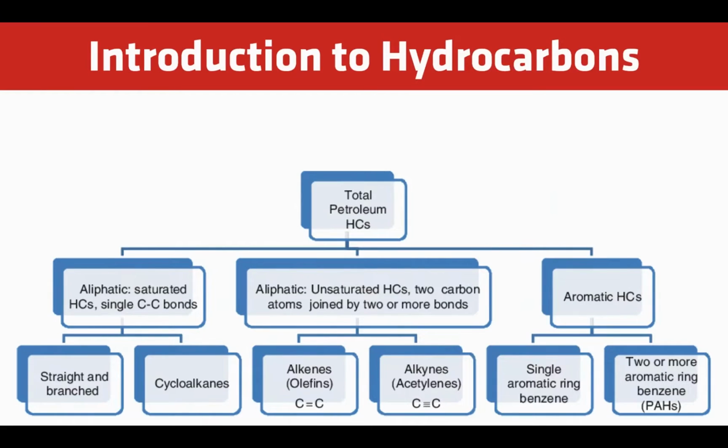There are three main categories of hydrocarbons, characterized as total petroleum hydrocarbons or total oil and grease. Saturated hydrocarbons include aliphatic hydrocarbons such as alkanes or paraffins, and alicyclic hydrocarbons such as cycloalkanes or naphthenes. Unsaturated hydrocarbons include olefins and alkenes. They're not usually found in crude oil but are produced in refinery cracking processes. Aromatic hydrocarbons are characterized by a benzene ring structure.